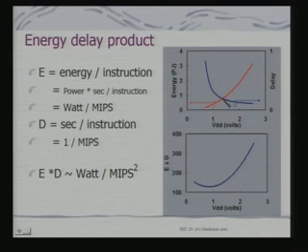And because of these phenomena, you would like to look at it as one quantity, what is called energy delay product. Now, why is this energy delay product important? Because it tells you that if you are really reducing VDD, and that reduces energy consumption, then you may need to pay in terms of efficiency, the time taken for execution of the code. So, if you want to look at this trade-off together using one measurable unit, then you use energy delay product.